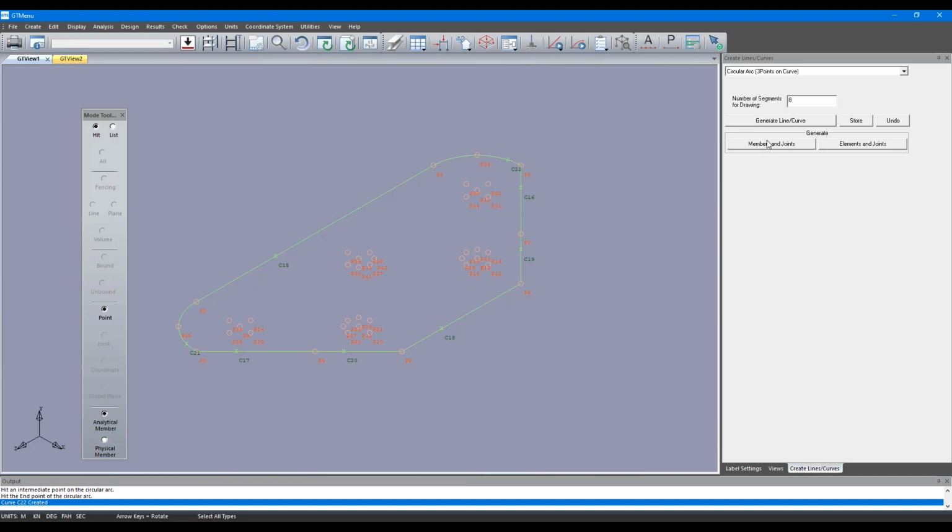Okay, so we create those boundaries, and then we'll create some internal boundaries, which represent holes of a plate. So we've created the 3 points on these holes, and these green lines now internally represent openings. Once we do that, we just have to do it for 3 more holes here. We can then use a new tool to do the meshing for this plate.